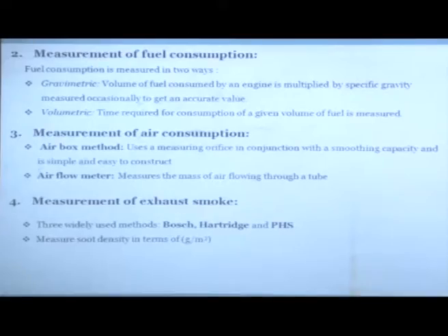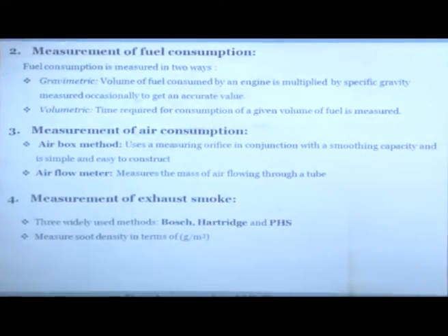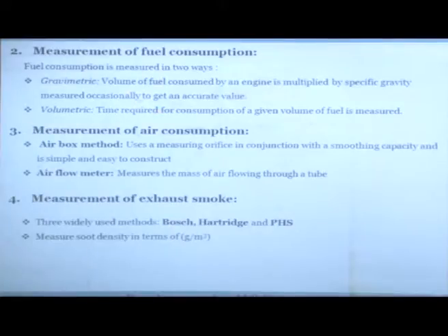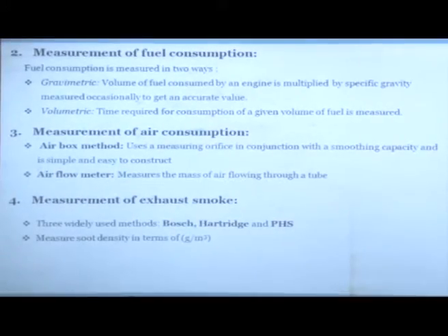So for the gravimetric method, you can use the volume of the fuel consumed multiplied by the specific gravity, or you can directly measure the mass of the fuel consumed, and that is more accurate. If you are doing the volumetric fuel consumption measurement and want a correct result, it is a good idea to also record the temperature and the density of the fuel at that temperature. If you use this data, you can convert your volumetric fuel consumption into gravimetric fuel consumption very accurately. Is that clear?